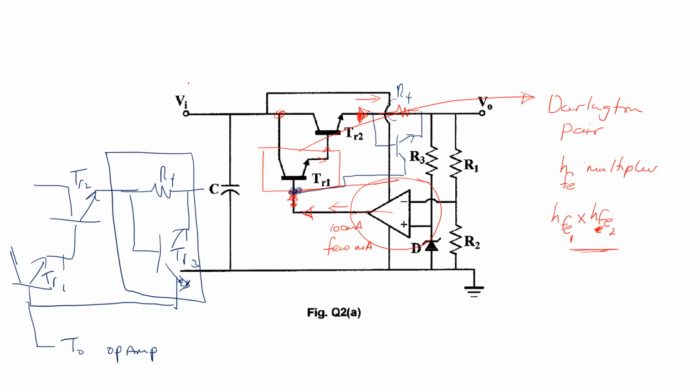One, you remember how an op-amp works, the virtual earth behavior, so that allows you to calculate voltages, for instance, at the two inputs of the op-amp. And then from there, everything else is largely normal circuit analysis: currents, voltage, resistances, and so on.